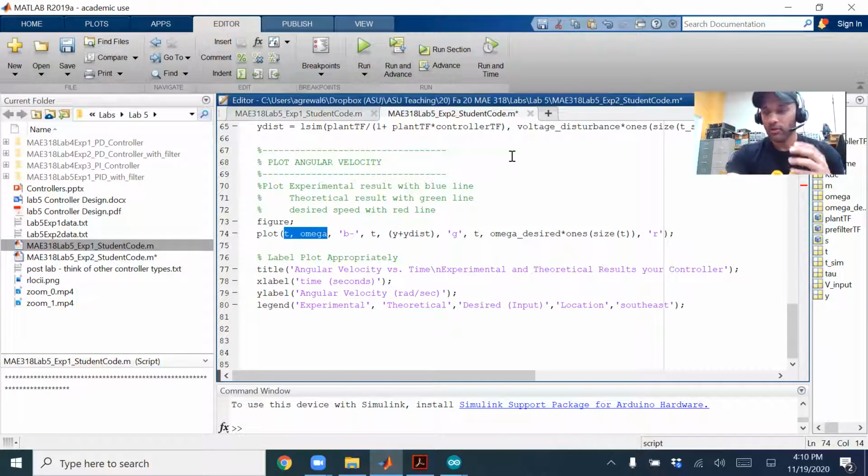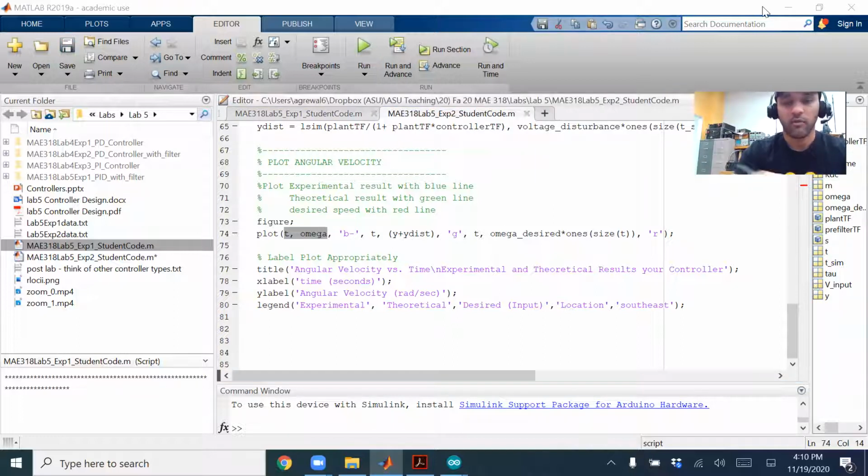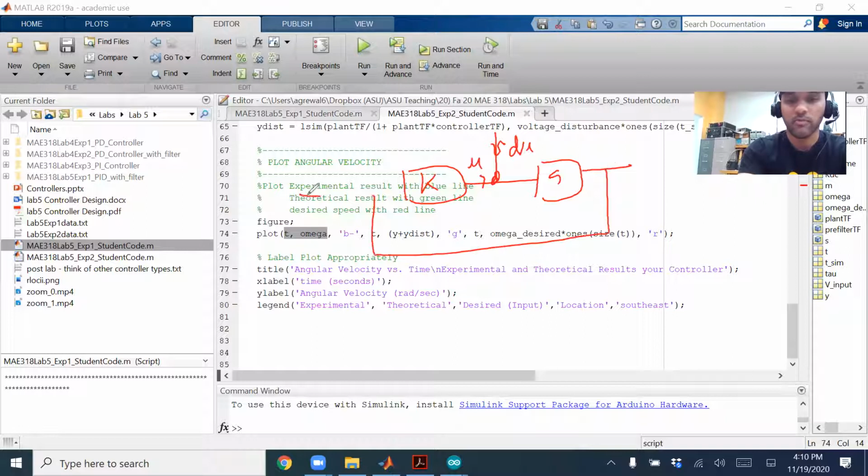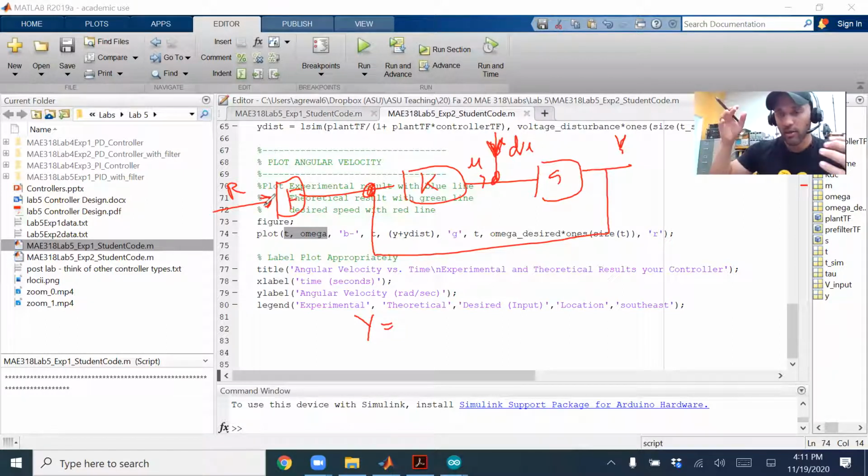Okay, let me explain briefly how this mathematically is functioning in case this is not clear. Let's annotate over here. So this is my system. There's a G, there's a K, and the input to the G is both the disturbance, which we call du, and the output of the controller. No H, but there is a pre-filter on the reference command. So for the output y of this system, there are two real inputs: one is du and one is r. These are flowing out of thin air into the system, as in we decide them. Every other signal in the system is interconnected.